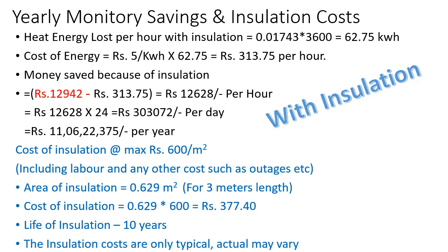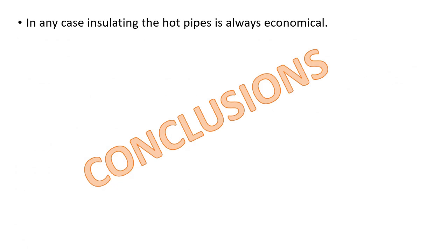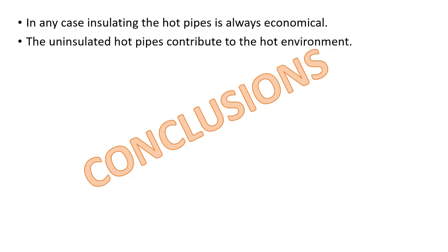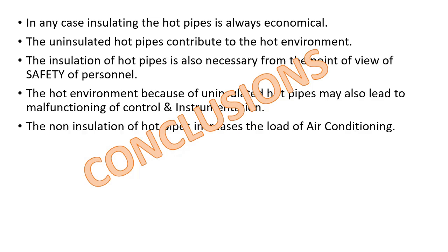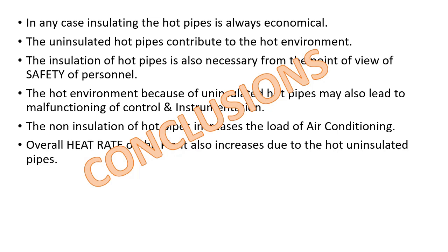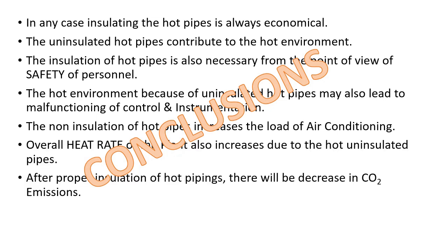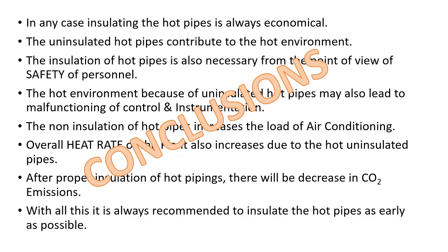So these are the conclusions we can draw here. In any case, insulating the hot pipes is always economical. The uninsulated hot pipes contribute to the hot environment. The insulation of hot pipes is also necessary from the point of view of safety of personnel, because if somebody touches it, there may be a severe burn, so an accident may occur. The hot environment because of uninsulated hot pipes may also lead to malfunctioning of control and instrumentation associated with that particular floor or environment.